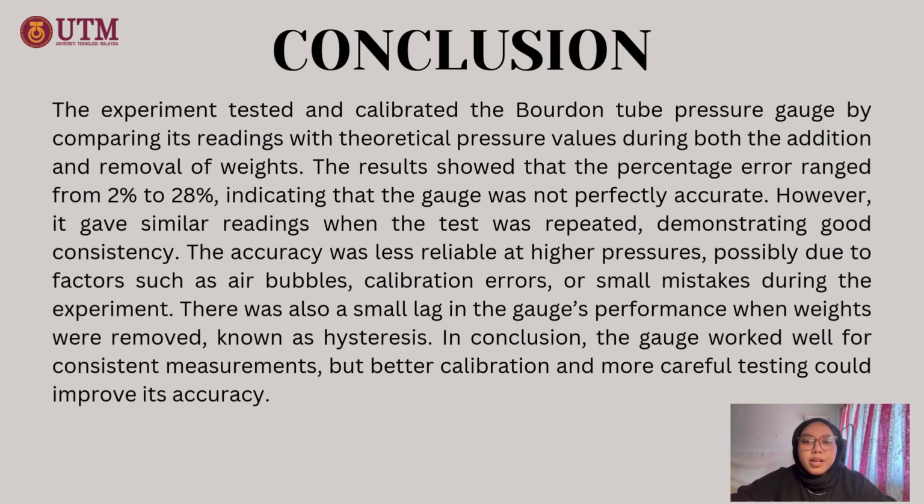There was also a small lag in the gauge performance when weights were removed, called hysteresis. In conclusion, the gauge worked well for consistent measurement, but better calibration and more careful testing could improve the accuracy.